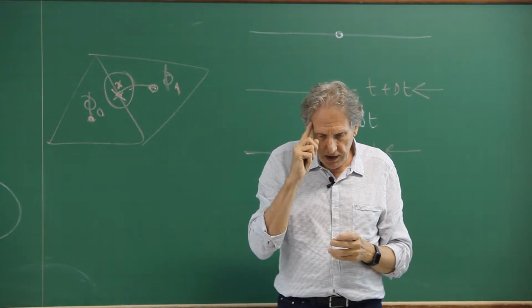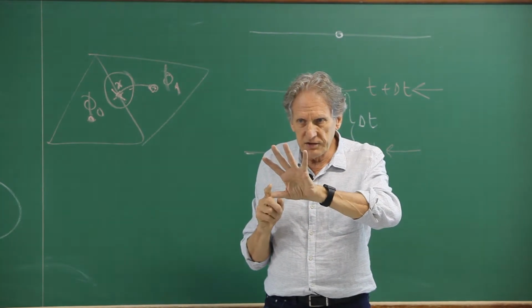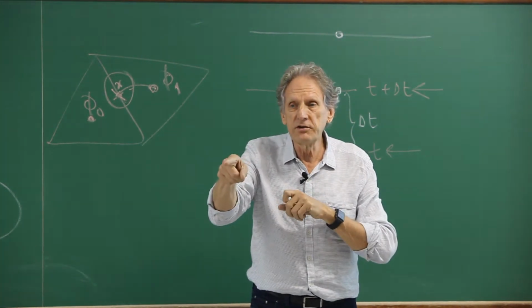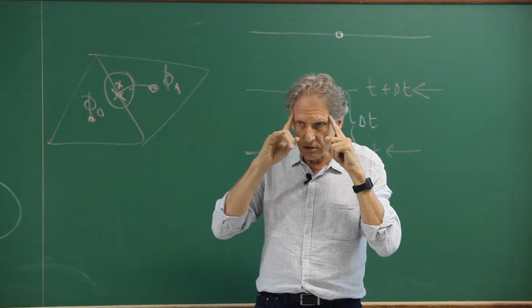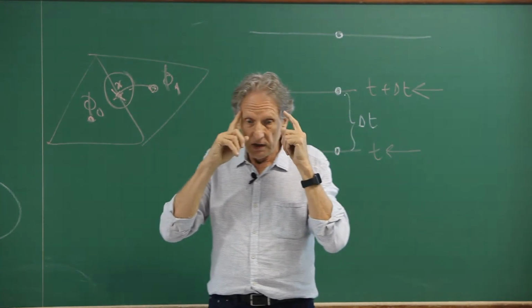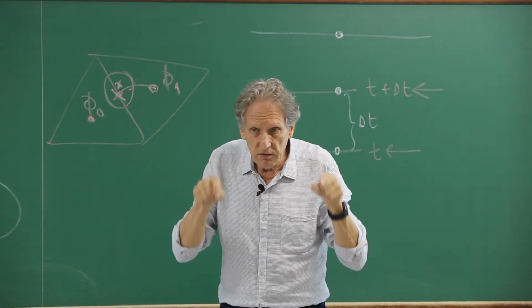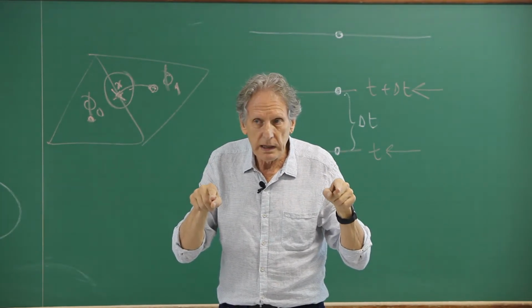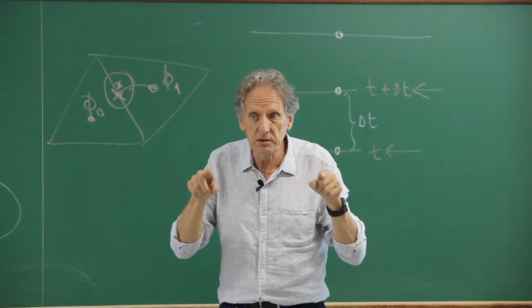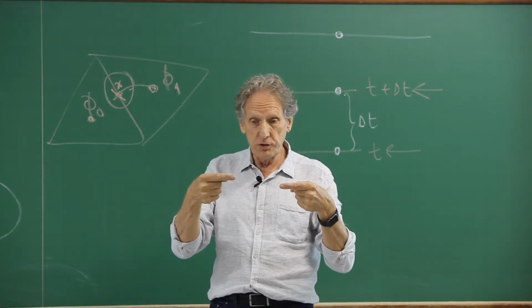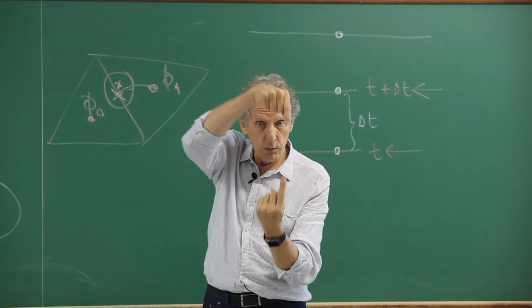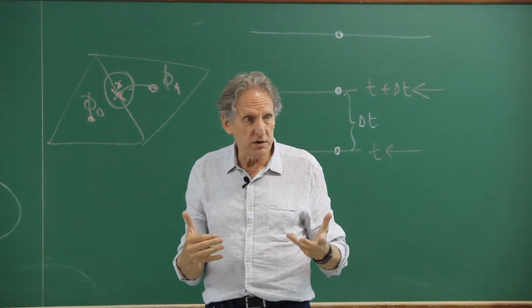So just to think that the grid is inclined with the flow, then there is numerical diffusion, it's wrong thinking. Because this happens if you are using an interpolation function which is not a good one. If you insist on keeping 1D and 1D in a 2D problem, of course.